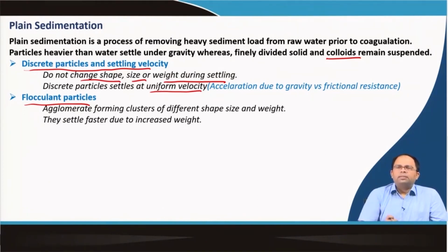I will explain why it is important, because that will determine the time for which you have to keep the water inside that particular tank. You have to give that time for these particles to actually settle down, right. So, the time you retain water in a sedimentation tank depends on its settling velocity. This is determined based on acceleration due to gravity, because it is falling down due to gravitational forces, and the frictional resistance of the liquid. It is a combination of both that results in the settling velocity.